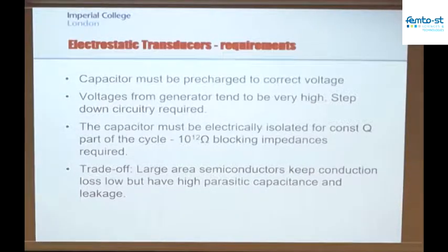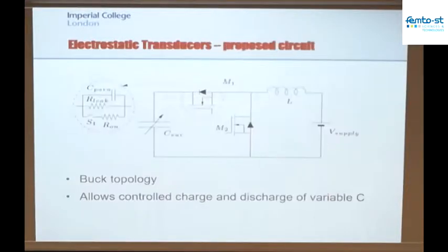All of these things, in a circuit that's processing hundreds of milliwatts or watts or kilowatts, tend to be inconsequential. Well, then you have to think about them in terms of losses and heat dissipation, but in terms of fundamental operation of the circuit, you don't really worry. In a harvester, these bits of energy you need to make the circuit switch on and off can be really fundamental as to whether you can make something work or not.